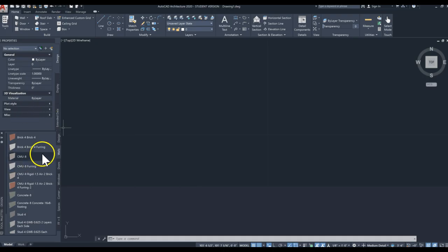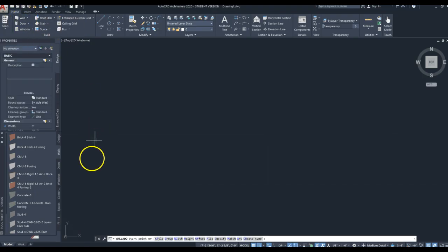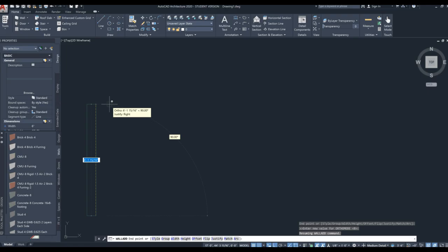All right, to get started, let's click on Home and then click on Wall right here at the top. Okay, to start drawing your first wall, you click once in the workspace, and hey, there we are. Notice that white floating box. It shows you how long your wall is, and you also have this angle measure appearing. Hold down Shift on your keyboard and check out what happens. Now it snaps your wall into place. It can snap onto the y-axis or the x-axis, which is pretty cool.